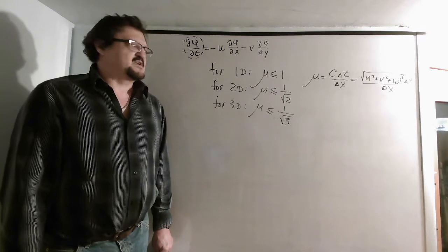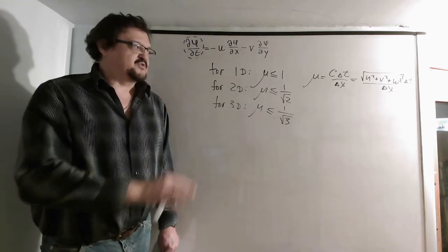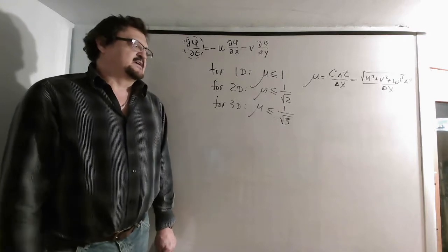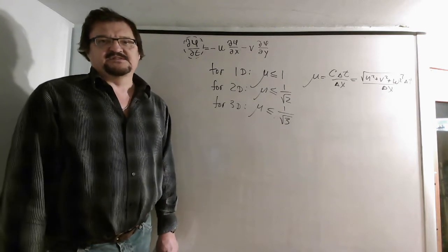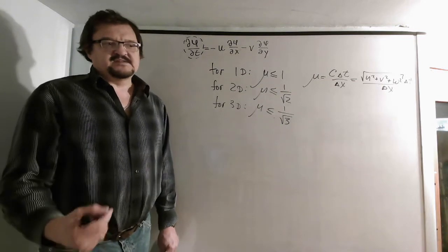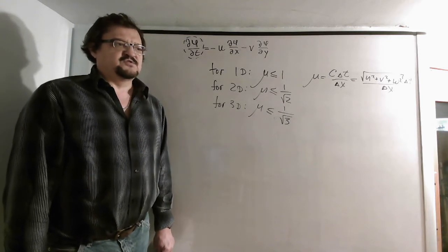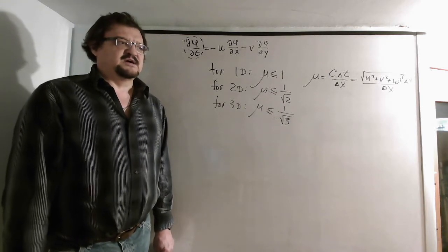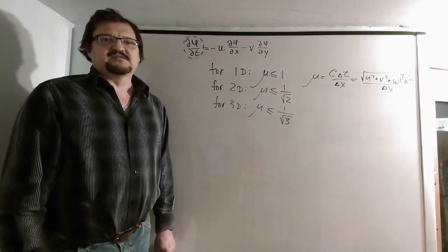Don't just assume that theoretical limits are correct, because otherwise you may have stability problems with your model and not even realize that it's a stability problem. All you have to do is just reduce the time step. It is actually a good test. If your model blows up, there are many things you need to look at.